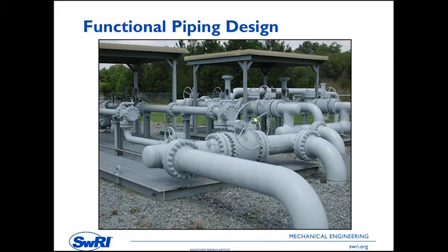So I guess the potential problem that would be exhibited with this configuration is you could develop a full body rotation, a swirl, and you have a concern now with the meter type that you select. Will that meter be able to handle that swirl and interpret it correctly in terms of flow velocity, mean flow velocity in that meter tube?